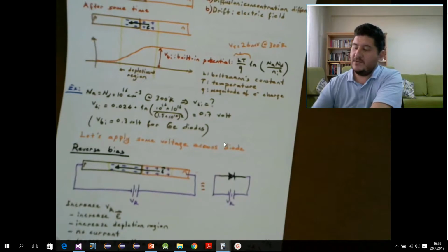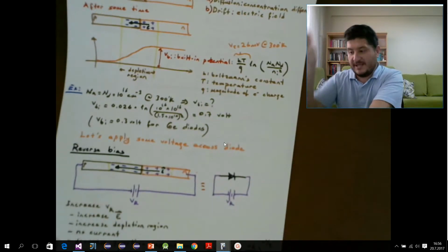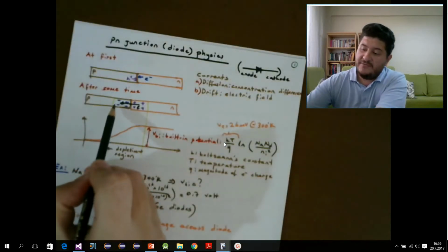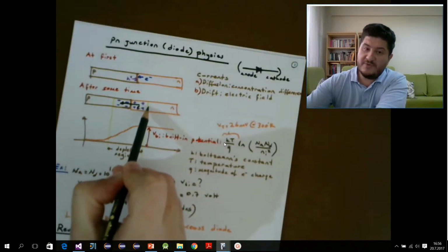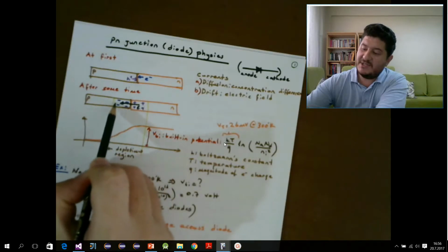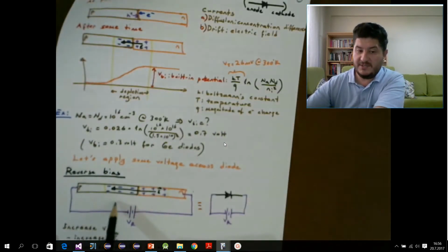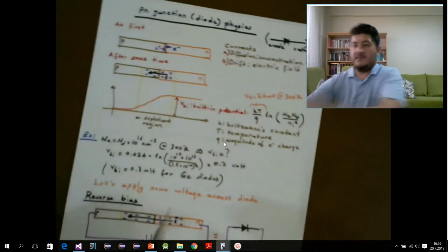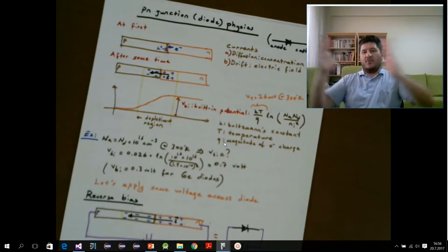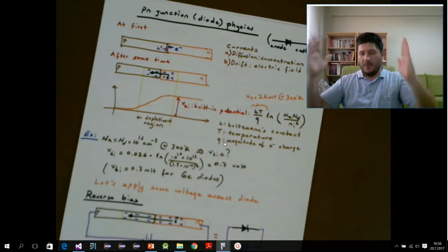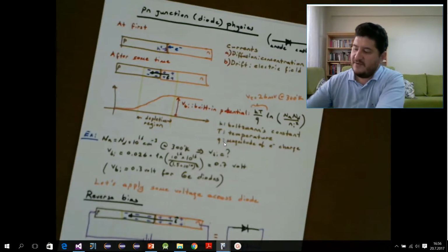Okay, so there will be no current when we raise that gap. The only thing that's happening is if we have a capacitance from this point to this point, since the depletion region is getting bigger, that space is now wider. If that depletion region is getting wider, that means we have less depletion region capacitance.